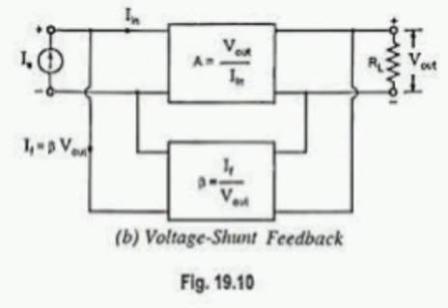IC equal to B0 plus B1 cos omega t plus B2 cos 2 omega t plus and so on, Bn cos n omega t. Percentage of Dn equal to modulus of Bn by modulus of B1 into 100%, where n equal to 1, 2, 3 and so on. Here the fundamental frequency component has the amplitude B1 and the nth harmonic component has an amplitude of Bn. Thus total harmonic distortion percentage D equal to root of D2 square plus D3 square plus D4 square and so on, Dn square into 100%.